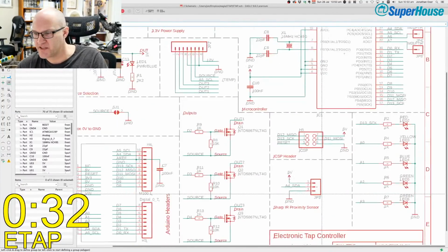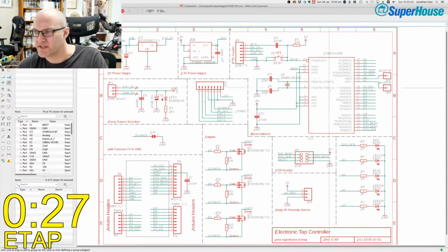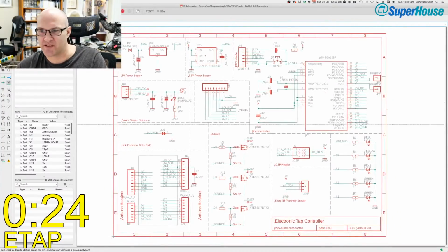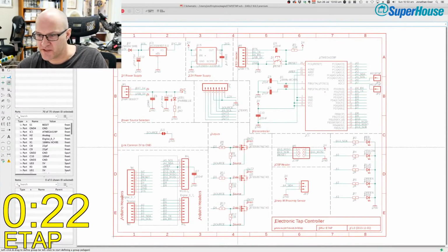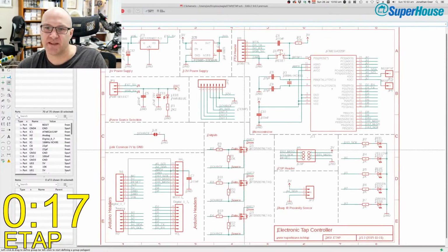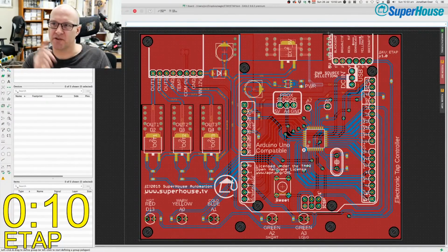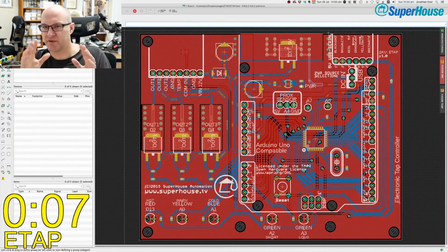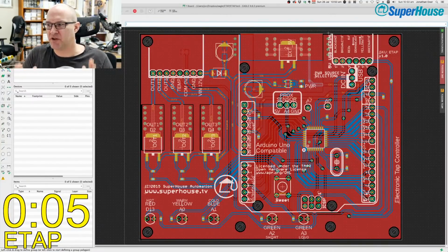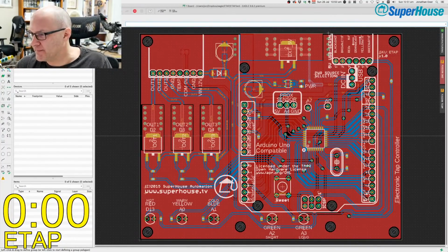I've got to orient myself. Oh, here we go. Sharp IR proximity sensor connects into here, and there's an ATmega. So basically this is, once again, like an Arduino. It's even got an Arduino shell on there. It's got a couple of MOSFETs here, which it can use for switched outputs, and that's what fires the solenoids inside the tap for hot, cold, and warm. Because the way those taps typically work is they have the hot and cold pipes coming to a T-piece, and there are 3 solenoids, and you can have hot, cold, or warm output on the tap.